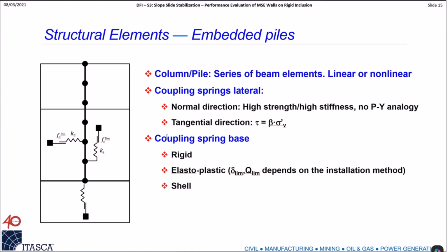When we apply a force in the vertical direction, the interaction along the shaft is a very thin layer of soil that provides the shaft resistance. It is not meters of soil around the shaft that actually react vertically. It's just a thin layer. It could be a couple of centimeters or even less, depending on where you are along the pile, that actually provides the tau that reacts to the axial force.